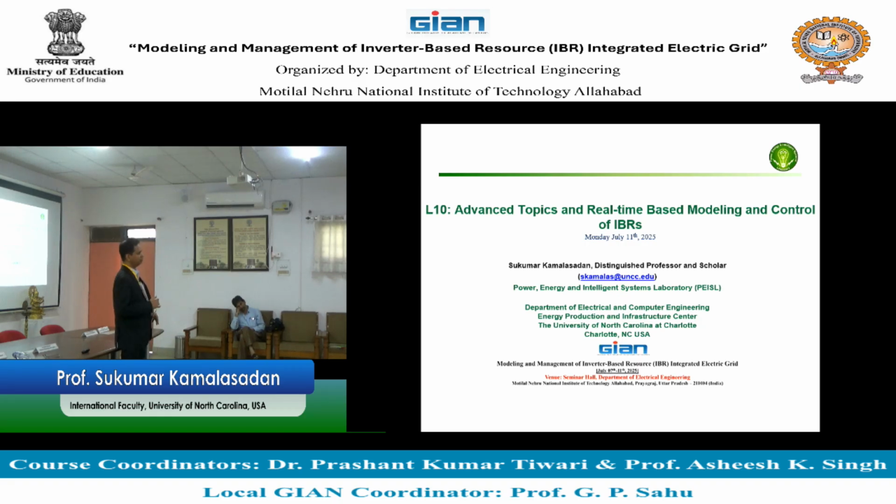Then finally, I told you an architecture which is called unified, which means not following or forming, but working in both conditions, connected to the electric distribution system, which can be run for unbalanced cases as well, for positive, negative and zero sequence. And finally, I told you how this inverter control can be linked with the other controllers, secondary control and tertiary control, which we talked about yesterday, where at that time we said the inverter is just a red dot called DER, and then we talked about the grid. Now we go inside the red dot and see how this dot works.